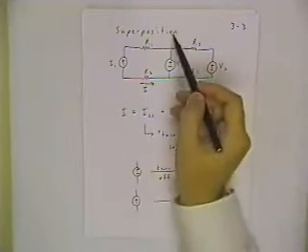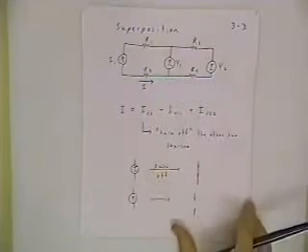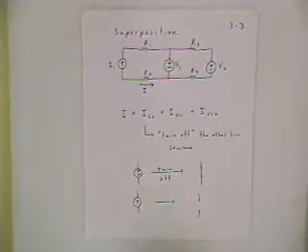So I would say superposition is more of a theoretical understanding to make op-amp circuits and some other circuit applications more understandable. It's not really a practical solution technique because, in essence, it doubles, triples, quadruples the amount of work that you have to do.